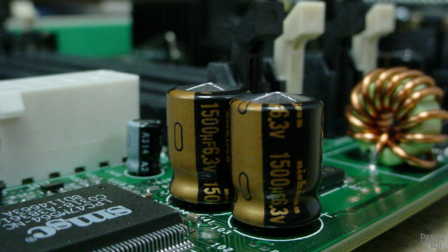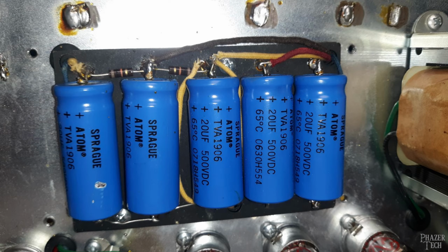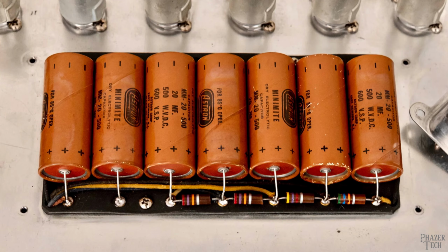Also, be careful when dealing with extremely high voltages. For example, tube amplifiers will have large capacitors in them that are rated for several hundred volts. And depending on the circuit's design, many of these capacitors will retain this voltage even after you unplug the amp. If you happen to open it up and touch one of these caps, it could be lethal. So it's common practice for amp techs to drain these caps before working on the amp. So again, be very careful when dealing with big capacitors that store hundreds of volts.